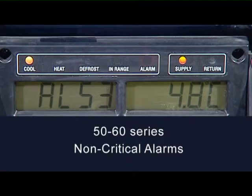When a 50 or 60 series alarm is activated, the alarm code will flash alternately with the set point when active. When a 50 or 60 series alarm is active, the unit will continue to run and maintain the set point temperature. The alarm light will not be illuminated for these alarms.